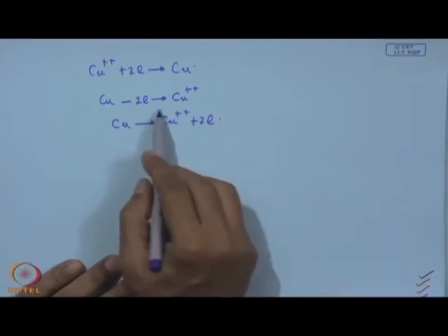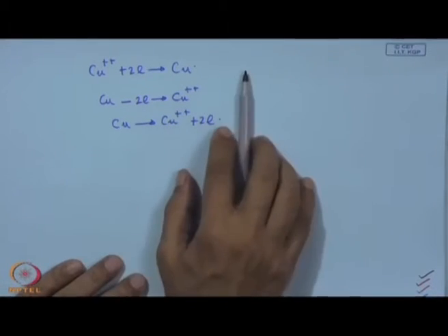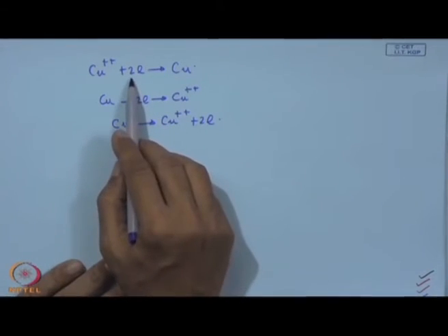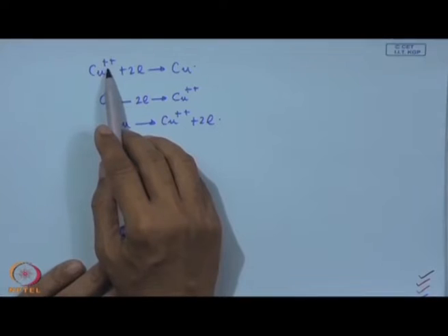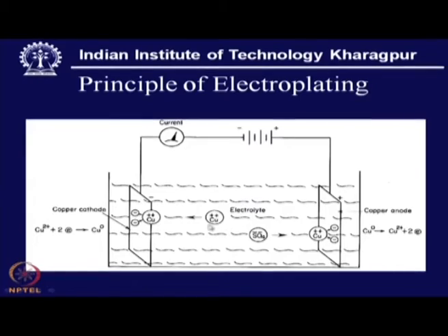These electrons which are released from the anode side are going to neutralize the copper ion which collects on the cathode side, and this way there will be a continuous flow of copper ion on this side which will be neutralized, and there will be erosion. I think we should say it is electrochemical dissolution.